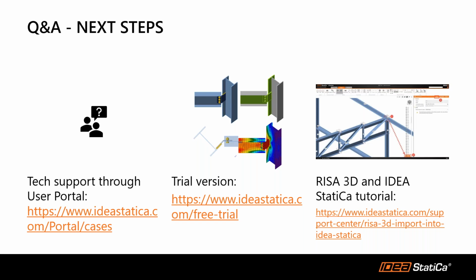Why do we need to change that column in Excel? So basically changing the LCS to the Z by vector, because they're asking, wasn't that already changed in RISA? Right. The one that we changed was the global coordinate system, and inside the SAF file, that's where we're adjusting the local coordinate system of every single member.